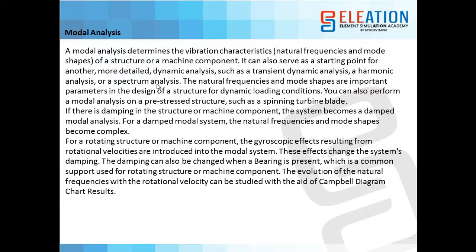Now one more thing which we are going to cover on the part of analysis is modal analysis on the roll cage structure. So we mostly perform modal analysis to find different mode shapes generated because of frequencies, say engine frequencies or road frequencies or atmospheric frequencies because of the motion. So we calculate these frequency ranges and we see how my component will behave in these frequency ranges.